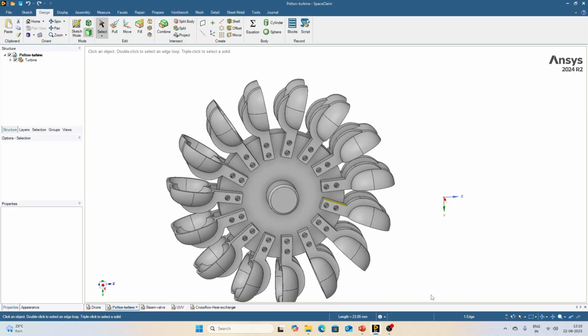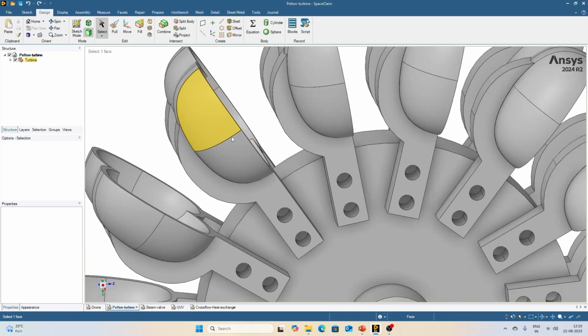If you want to select multiple objects at once, then you can hold down the control key and select the multiple faces you want to choose. It can be either faces or edges or a combination. So in order to select multiple objects, you can just hold down the control key and select any object you want. As we were selecting the objects, you can see the information has been updated here. So right now, two edges and two faces are selected.